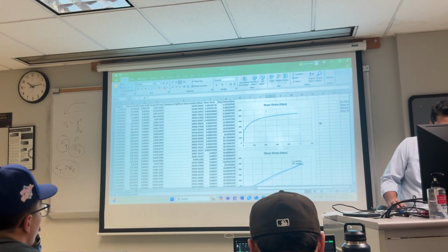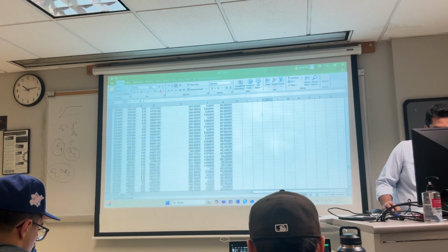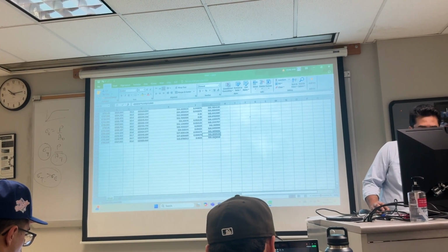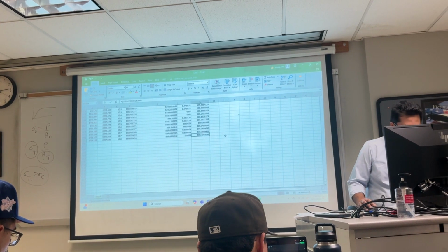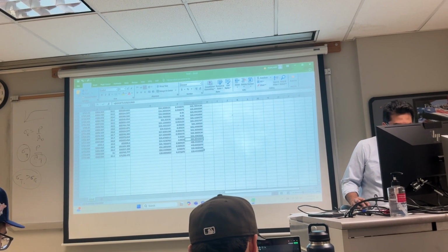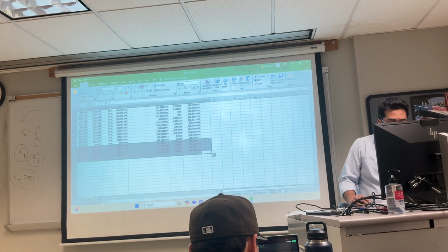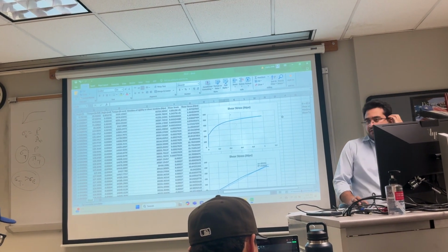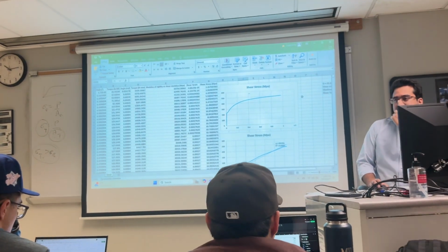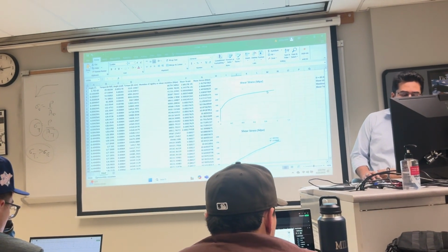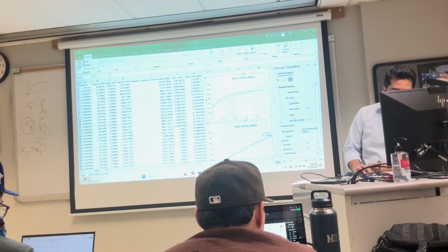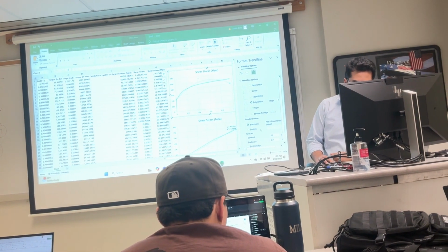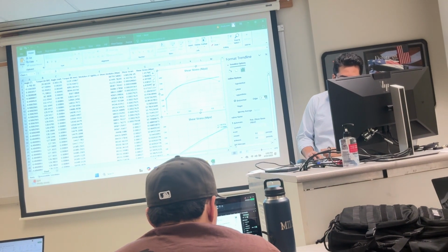See? Just the last 4 data where the stress is decreasing drastically, right? After the maximum you don't need it, no? I will retain this 504 too. Let's see. The last 4 data you can just delete, where the significant dip is. Yeah, perfect. After the significant dip you don't have to take it, right? So now do the trendline and make it polynomial. And let's see what will happen.